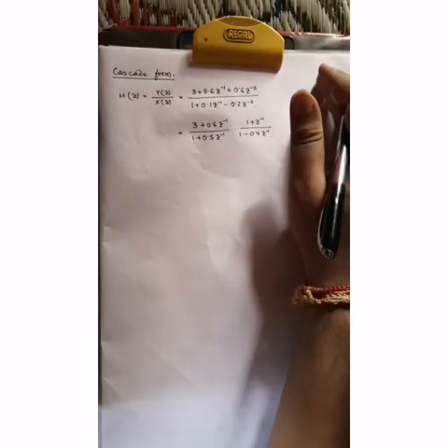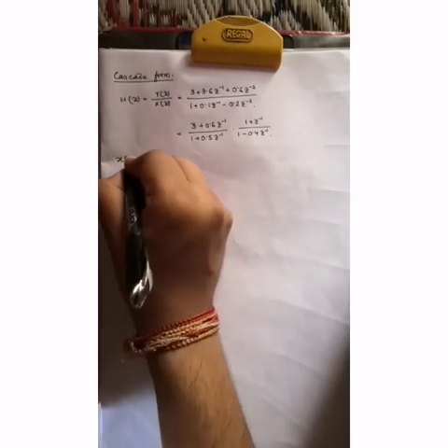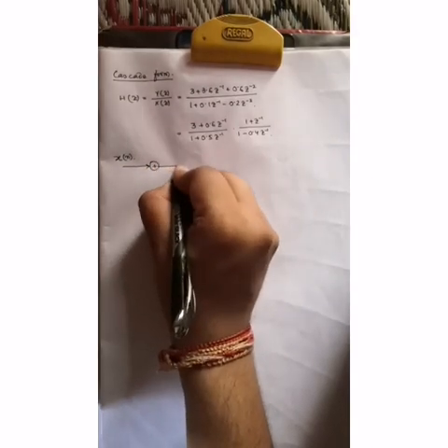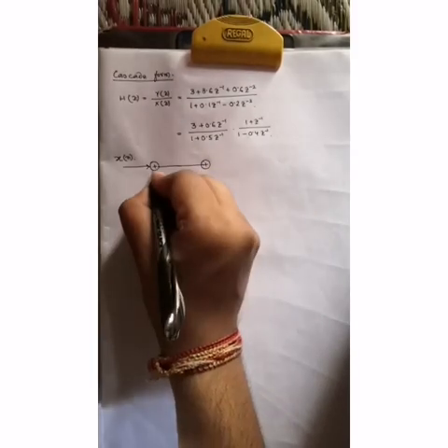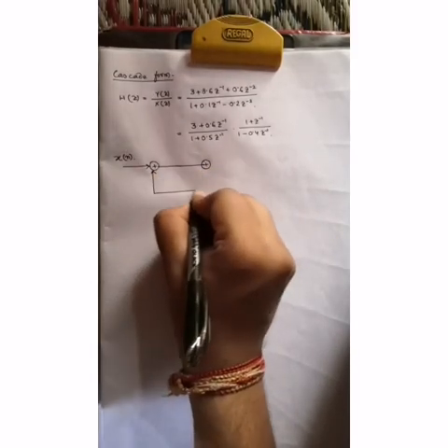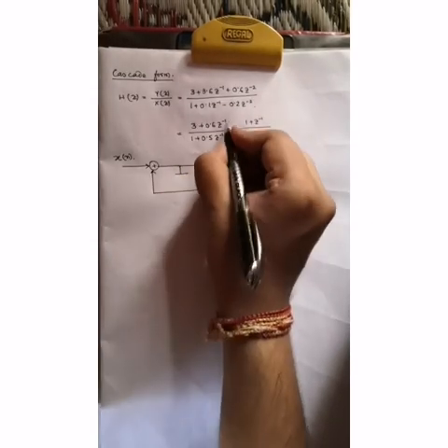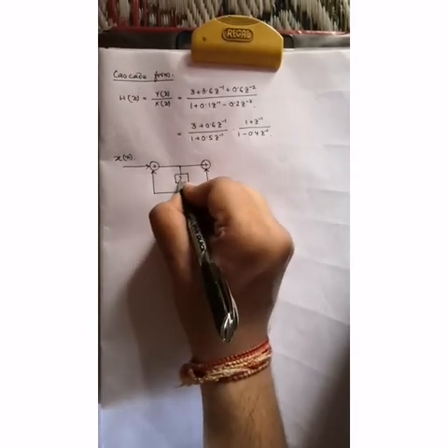So the form is basically similar to direct form 2. For direct form 2, x(n) is the input, one summation is there, another summation, and we need only one z inverse because the power is only z to the power minus 1.